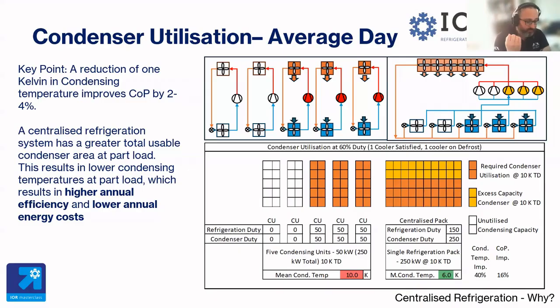Well, as we know, or hopefully will know or should know, heat transfer is, amongst other things, governed by the thermal conductivity of the material of the heat exchanger, the total surface area of the heat exchanger, and the temperature difference. And fundamentally, if for one system, for the same THR, the total heat of rejection that is, has more surface area, the temperature difference reduces, which means we have a lower condenser temperature. So here, for the same duty, we have a mean condenser temperature difference of 6K versus 10K.